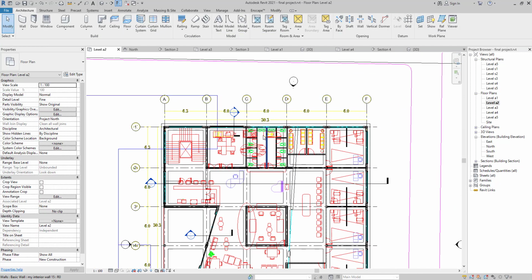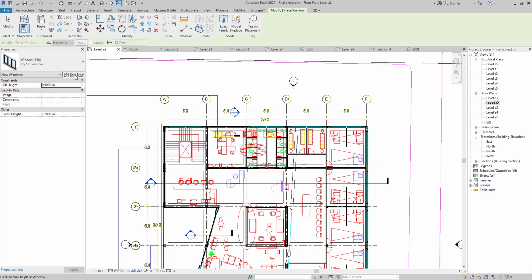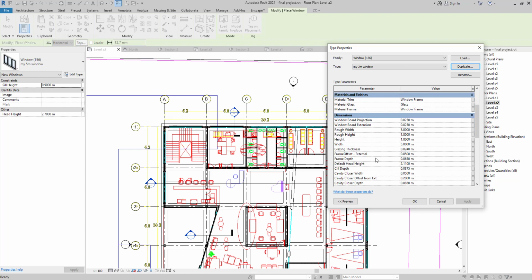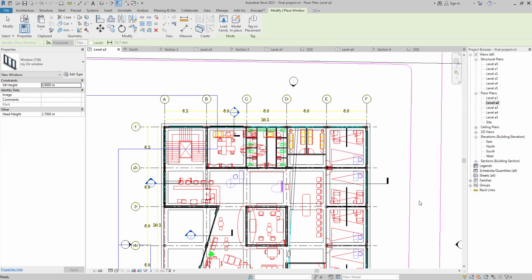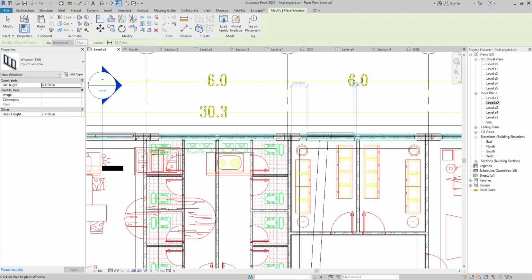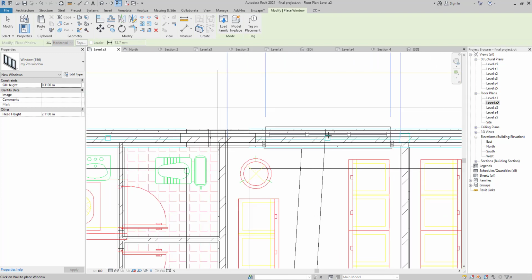The next step is to go create a 2 meter window. I'm gonna go to edit type, duplicate my previous window, change it to 2 here, and delete this number. Then I'm gonna go down dimensions, and I'm going to change my width to 2 meter, and click OK. After that, we are going to have a new window by 2 meter. 2 meter window for free glass is also fine. If you would like, you can change your window with 2 glass.